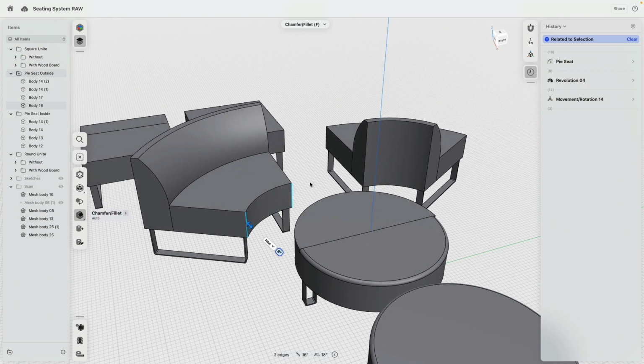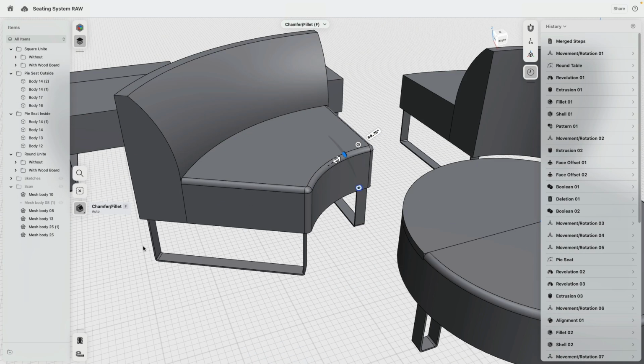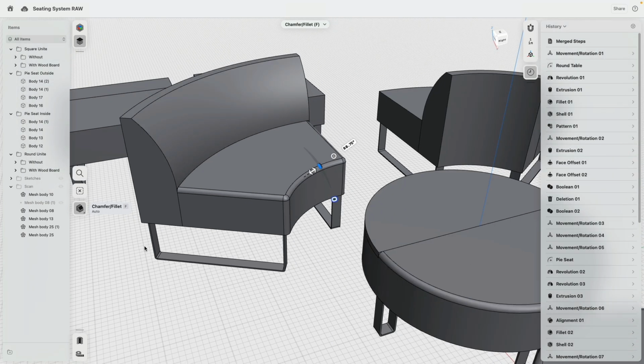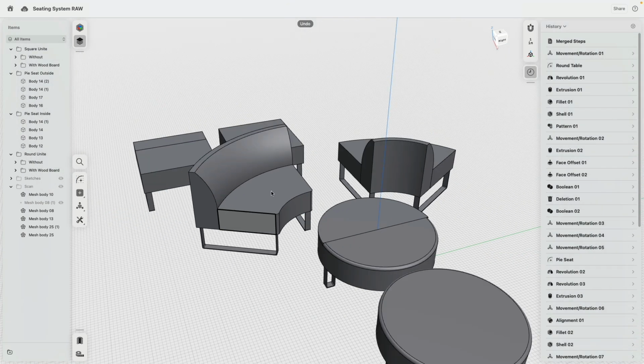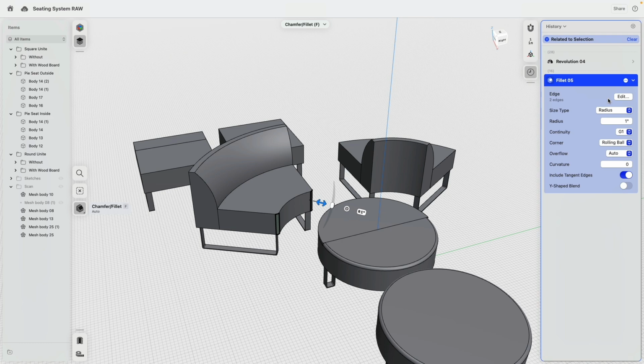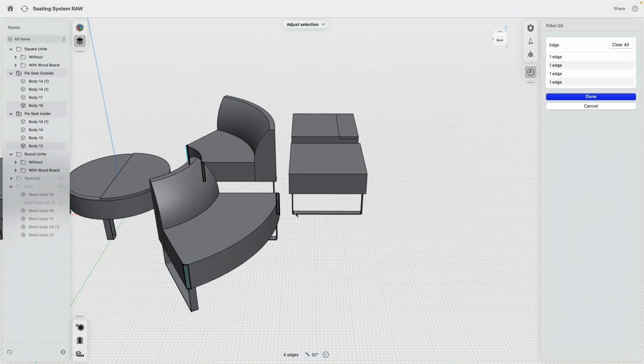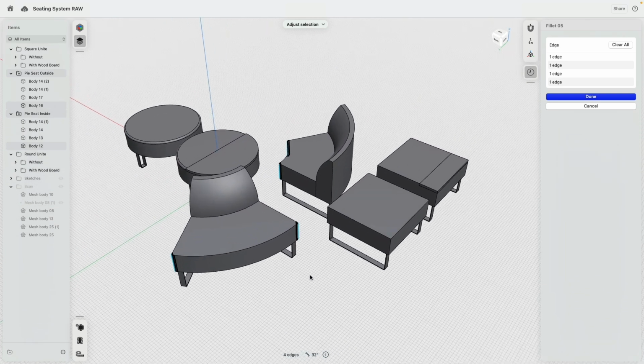Before I continue, I will select actually this corner here. So this will be the 0.75. So what happens if we do those with 1 inch? The main reason for 0.75 is that you can see I can nicely pipe those around. So that works very good. This feature, I would like to go back. Where is this one? There it is. Now I click this edit feature, edit edge, and I will select also here these two outside corners.